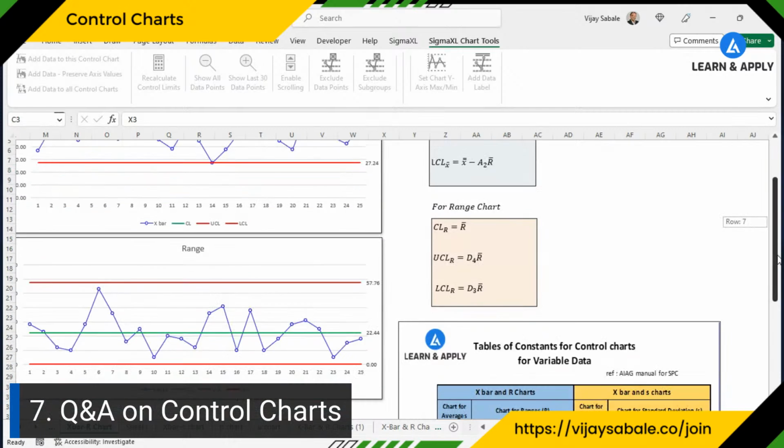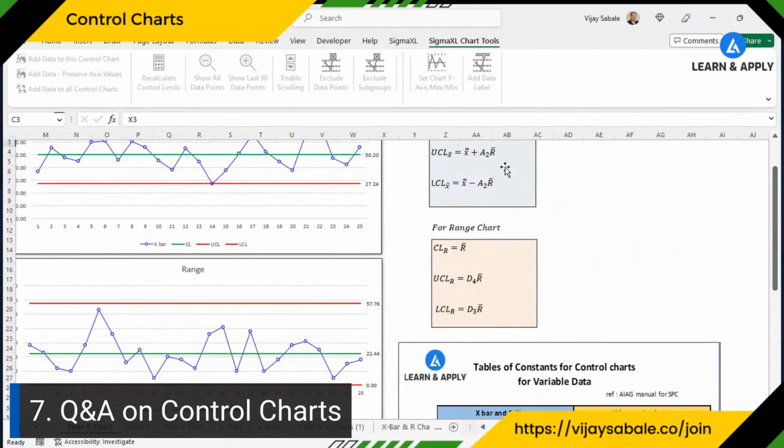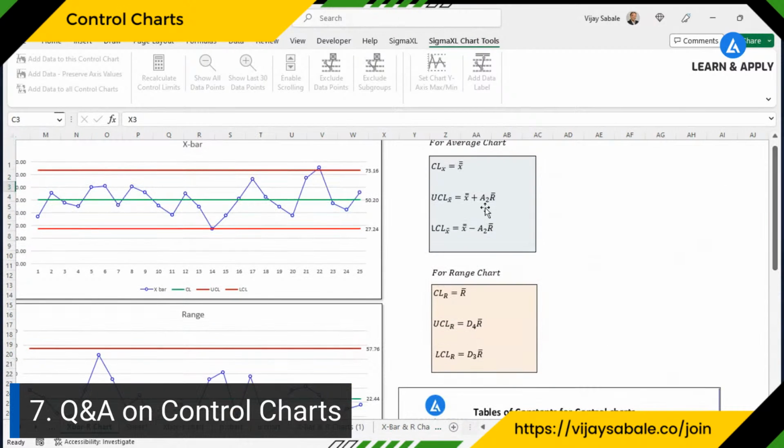For that purpose, we need to go here, A2. This A2 we need to calculate based on the subgroup size. Here we have the subgroup size as 3, so we can select A2 as 1.023. We need to add that value here, and R bar is nothing but the range. So we can get the upper control limit and lower control limit for the average chart.